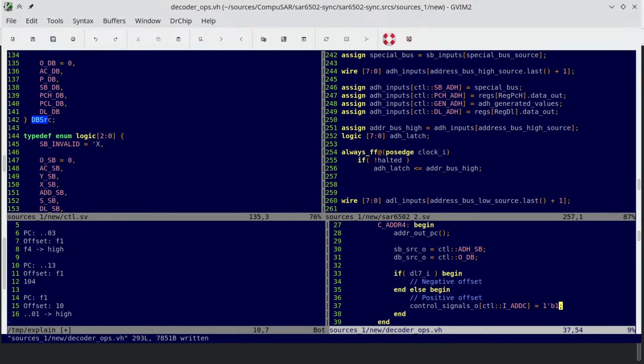What the ALU will do is assume there was a previous calculation that overflowed, which is correct, right? And add 1 to whatever result I gave on the inputs. So I gave it program counter high plus 0 plus carry, and that will give me a +1.